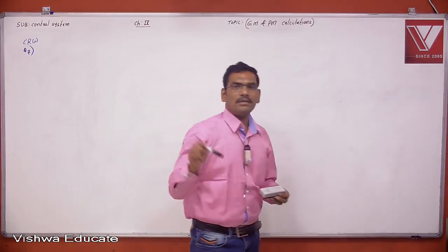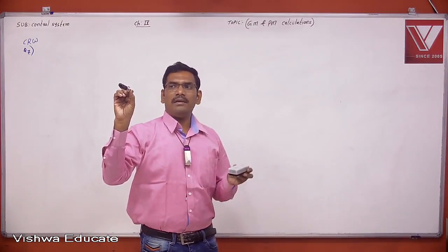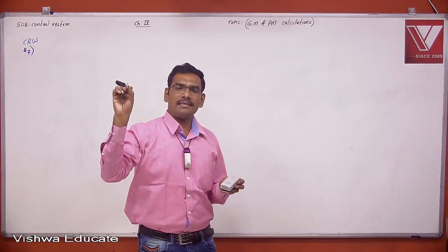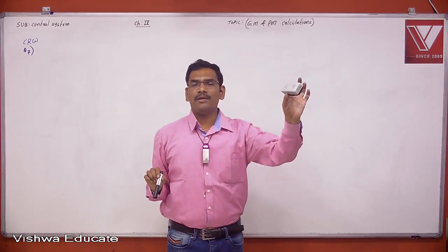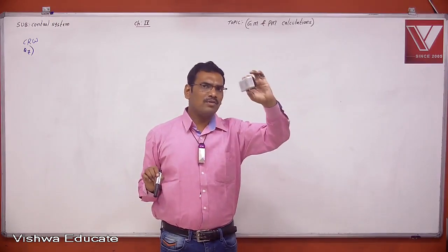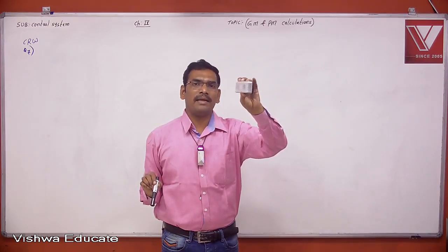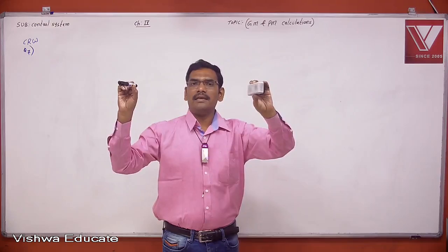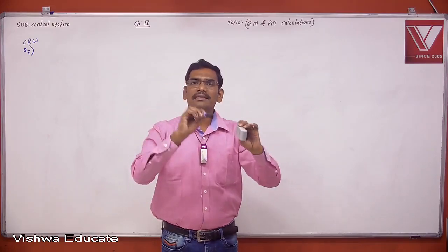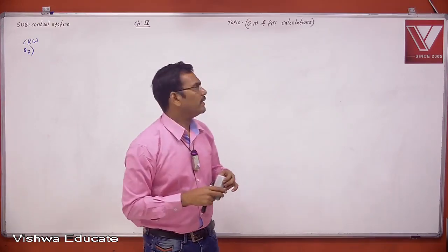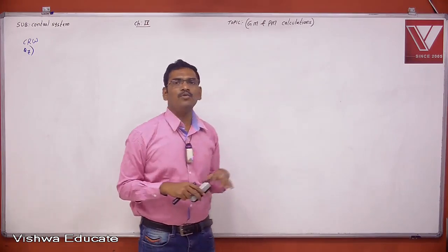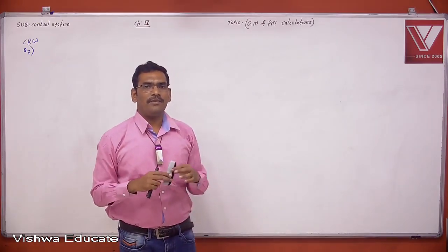I want to find the closed loop control system stability or analysis, but we have an open loop control system, whose frequency response is nothing but a Bode plot. Then in between these two, there is a mediator acting here. The mediators here are two, namely gain margin and phase margin.